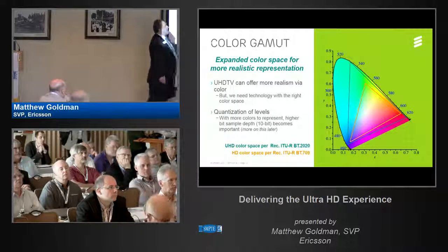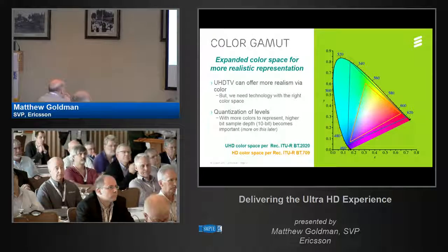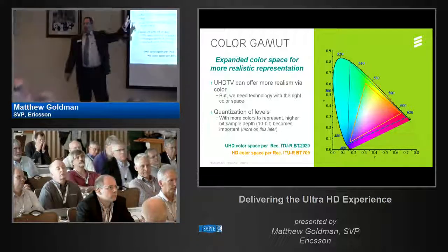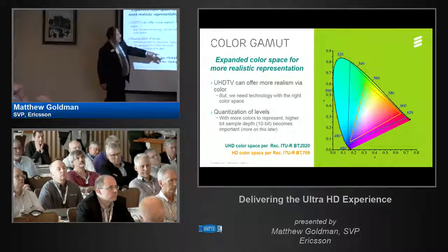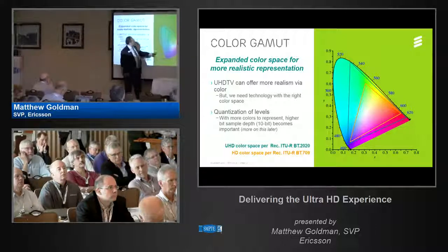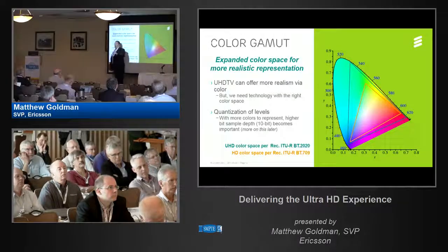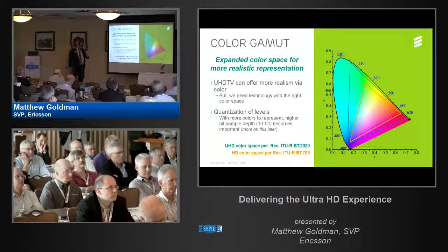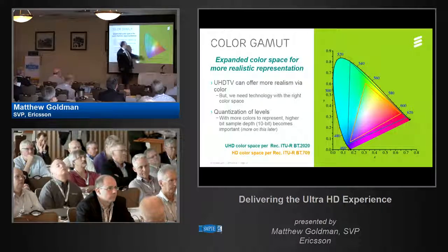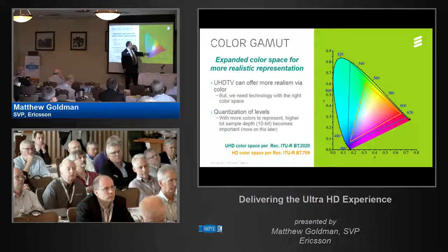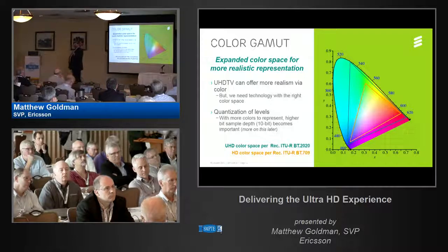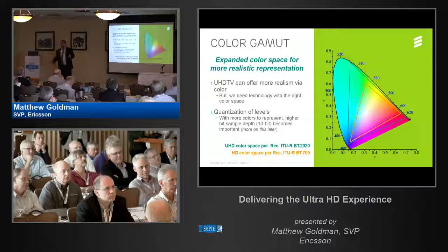This here is the visual surface colors that the human visual system could see, done as an XY chromaticity graph, just showing that it's in 2 dimensions, X and Y. There are 3 primary colors we use in television, red, green, and blue, RGB. Once you put those 3 points, wherever you put them, all you can do mathematically is draw straight lines between those points, because you only have 3 points to draw between.